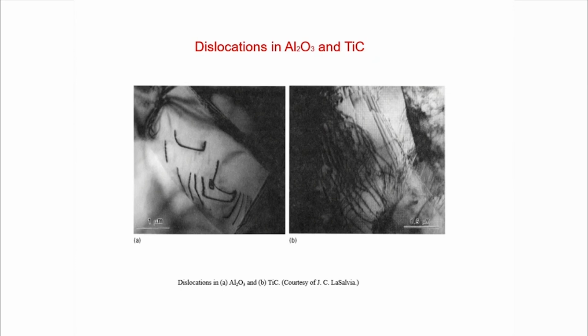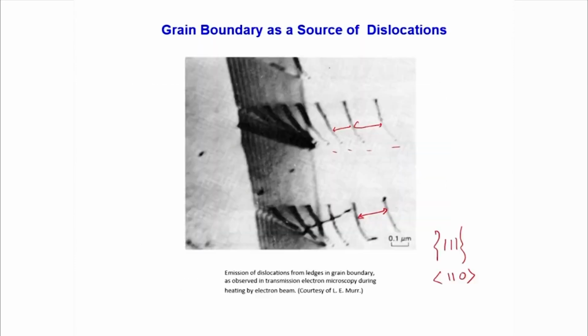But on the contrary, most of the metals and many ceramics do show plastic deformation, and that's why these aspects come into the picture. The Hall-Petch equation will be valid for those materials only. If you cannot generate dislocations, there will be no pile up, there will be nothing like a Hall-Petch.